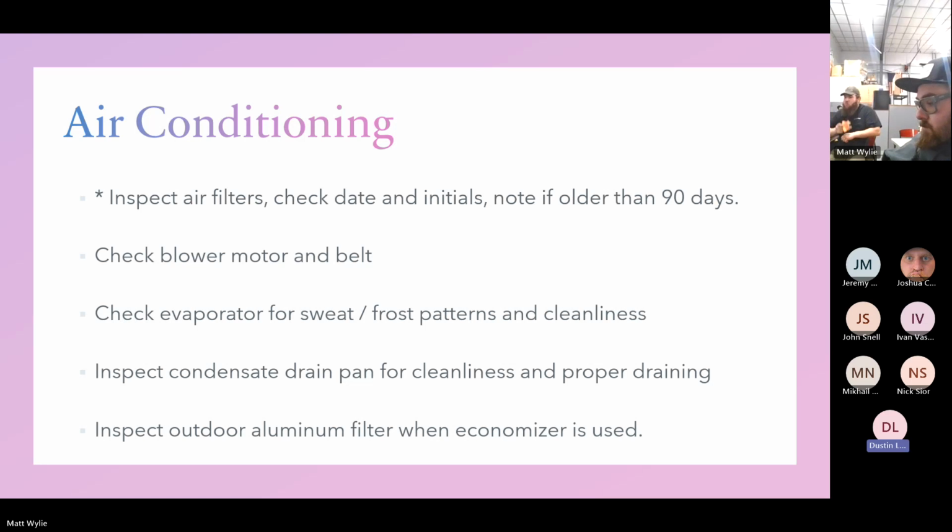Usually the motor pulley is adjustable on a lot of these. It's got 2 Allen heads. You can loosen those heads and you can actually twist your pulley to move it closer together or further apart from each other. And that's going to affect where your belt sits on that pulley and is going to increase or decrease the distance the belt has to travel going around, which will alter your amp draw and your fan speed as well.